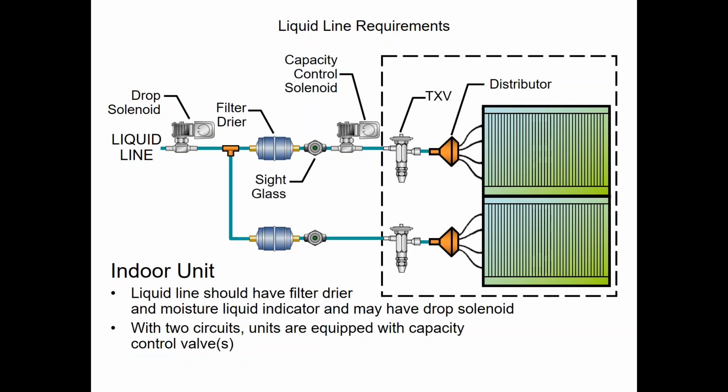And from there, then, of course, we have to accommodate for the evaporator. The evaporator, especially in commercial equipment, has some appreciable amount of refrigerant in it. Between all that, you calculate out a total weigh-in charge, and you may have to trim it by 1/2 pound or a pound, but if you measure accurately and your math is accurate, you can get within 1/2 pound to a pound of charge by the weigh-in method. And that's what we recommend nowadays.